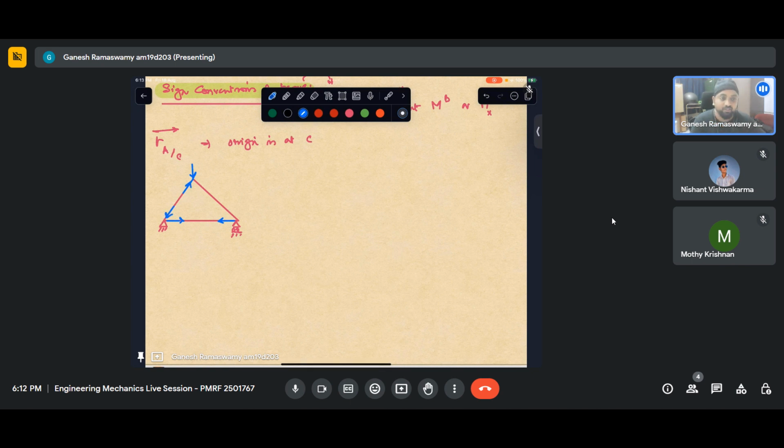So what is the convention here? We discussed briefly in the last session that in order to place the forces on the same side of the pin, which is the member side of the pin, we will be following a convention that towards the pin, if there is a member force pointing towards the pin, it will imply compression.